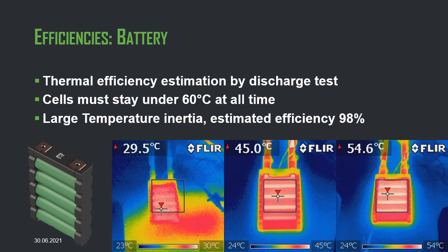During that test, we logged the energy, the cell temperatures and voltages until the cell is empty, or until the cell overheated hotter than 60 degrees, since afterwards the test would be unsafe.